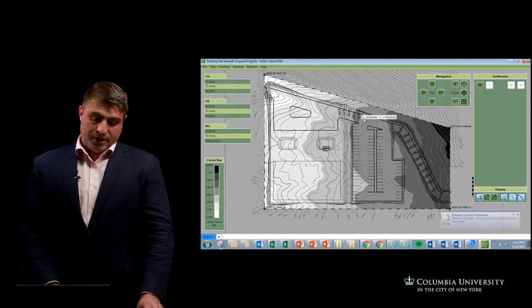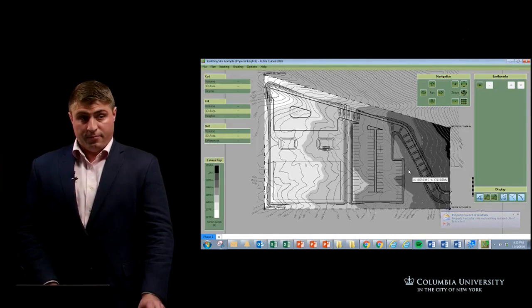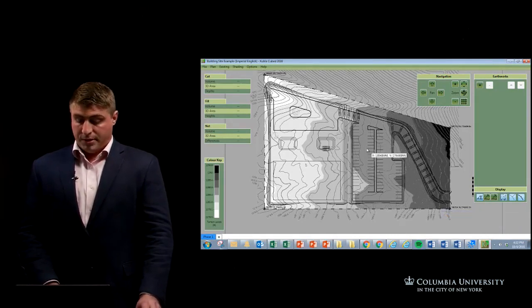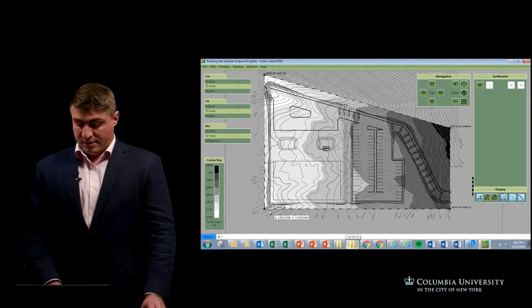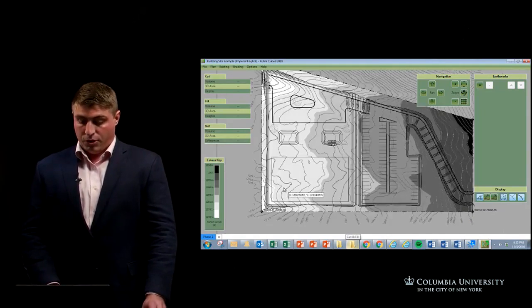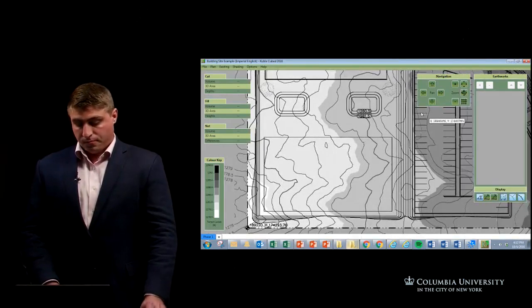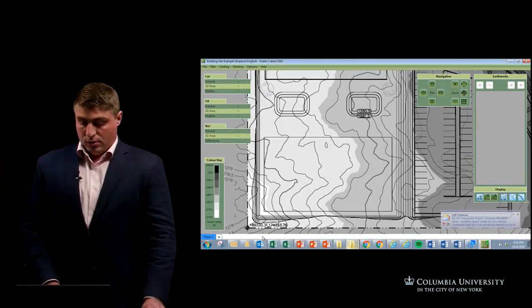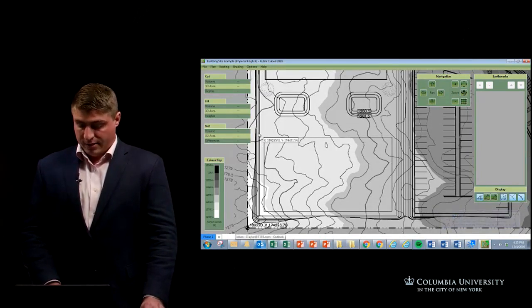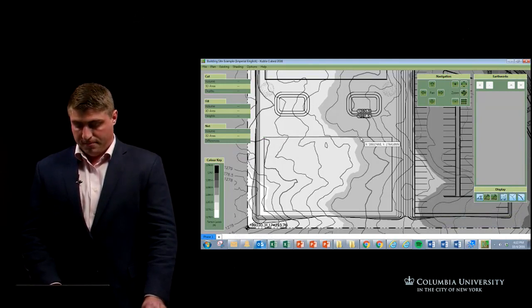All of the geotechnical and topographical data that we have been discussing earlier is already pre-populated into the plan, and it is crucial when doing cut and fill takeoff, as the software would be rendered useless without it. So quite simply, to get started, we're going to be quantifying a 100 tall by 200 wide site plan. And that begins by simply populating your points on the corners of the site.